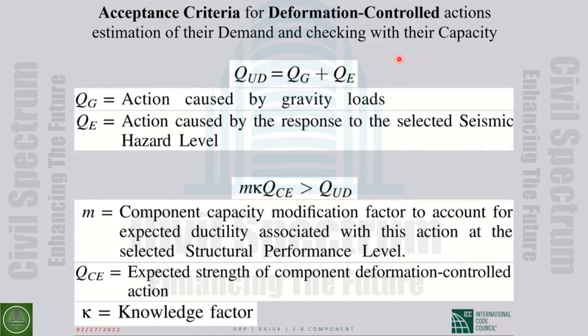Now we are looking at the responses. Some of the responses are dangerous ones, force control responses. We want to design them based on strength. We don't try to get help from the ductility, so just a strength design for them. They are force control. Some are the ones that have good ductility, and those are the responses that we selected to get damaged. They are deformation control.